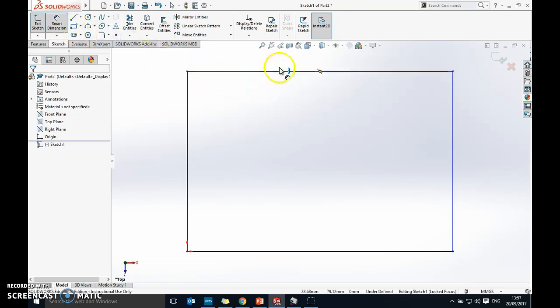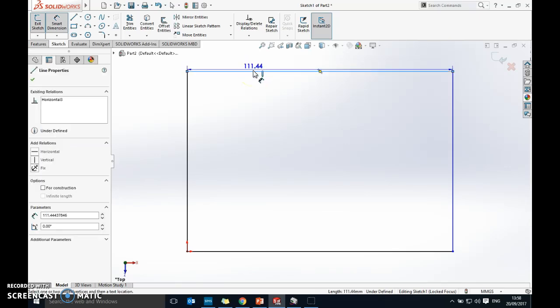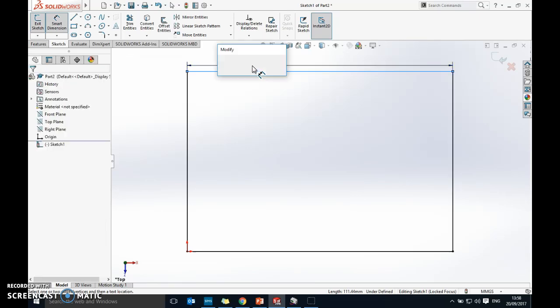First of all, if I hover over a line, it will go orange. Okay, when you do this, try not to pick the center of the line, because that might do something different. What you want to do is anywhere kind of in that 3/4 of the way along, or the quarter from the edge there. Okay, so I'm just going to grab that, left click and just move away, moving up a little bit so I can see the numbers clearly, and I'm going to left click.